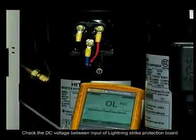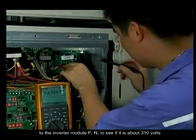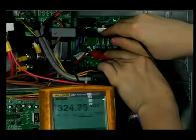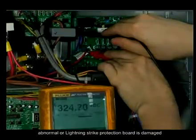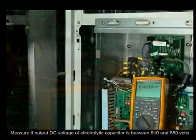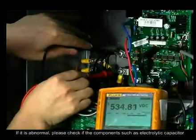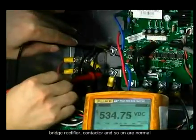Check the DC voltage between the input of the lightning strike protection board and the inverter module PN to see if it is about 310 volts, which is equal to 1.41 times the local input voltage. If it is abnormal, the voltage of the power supply is abnormal or the lightning strike protection board is damaged. Measure if the output DC voltage of the electrolytic capacitor is between 510 and 580 volts. If it is abnormal, please check if components such as the electrolytic capacitor, bridge rectifier, contactor, and so on are